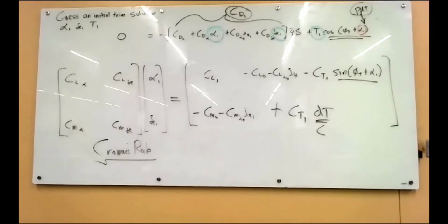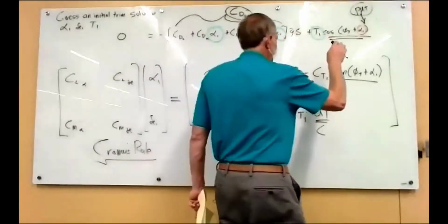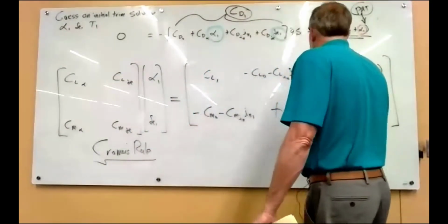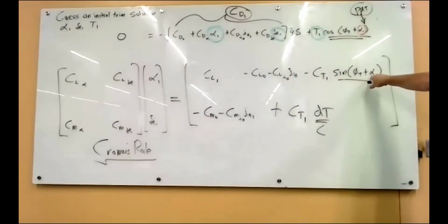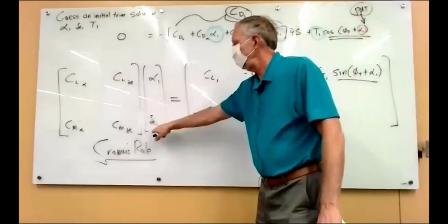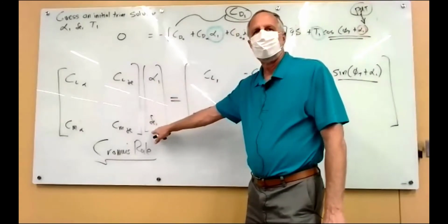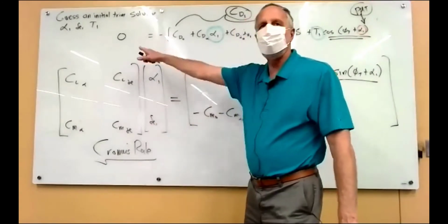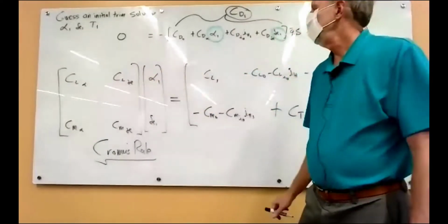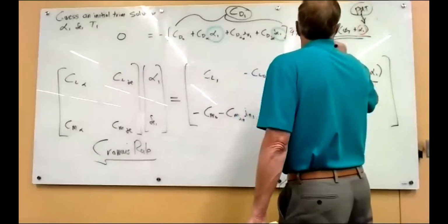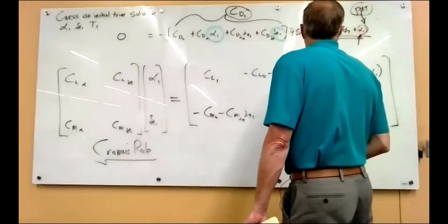Thrust, you don't even know what the airplane is. How could you? You know, 10,000, right? So you take those numbers and you stick them in here and here and here. And then you solve for a new alpha and a new elevator. It's going to be a little bit better because we just randomly guessed, at least these are going to satisfy this equation, right? And then we take alpha and elevator, the new values, and we stick it up here.